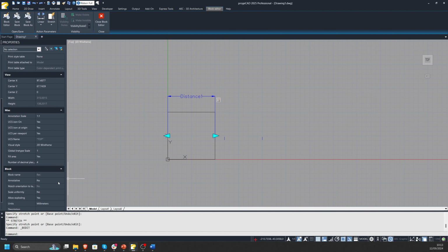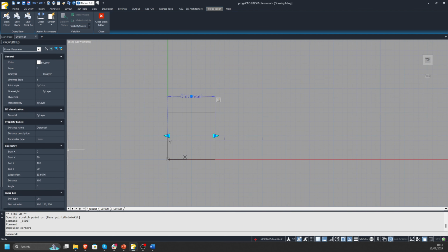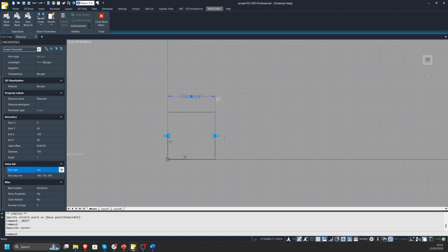And increments are something like lists, but a little bit different. Let's go and have a look. If you select increments, first we will need to address the distance of the increments. Let's say 25, minimum distance, let's say 100, because that's our table, and 200 is the maximum.